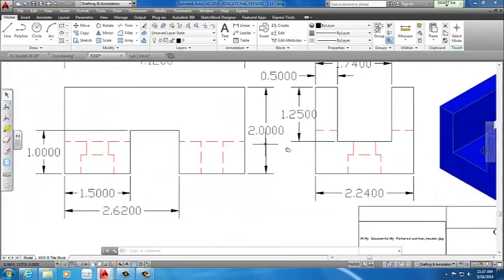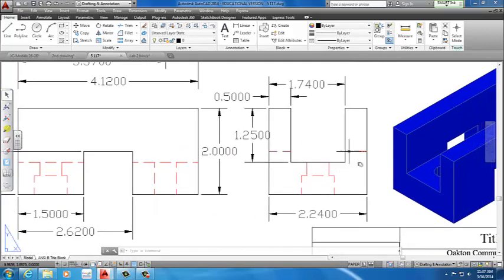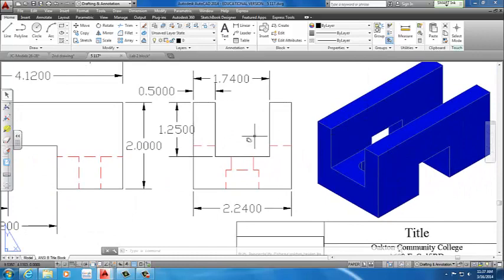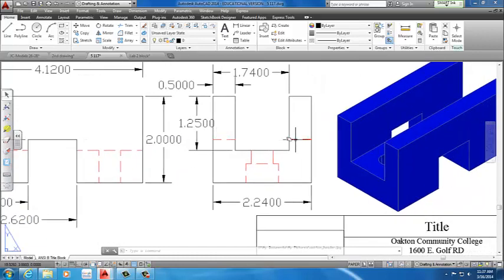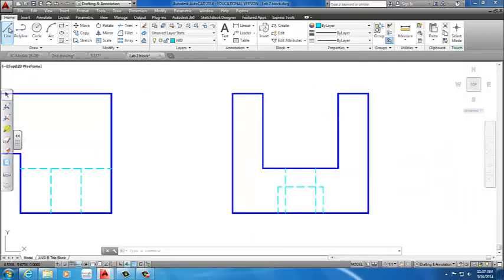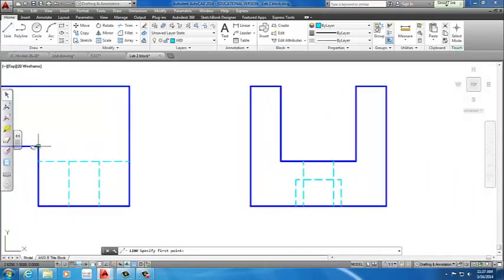I'm going to create a new viewport, a single section view from the center. I'm going to just create a box which is incorrect. But we do have to draw these two lines out here, so I'll double click inside, again, and use the line command. We can see the 3D object only, so I follow this line to give us a path. I change my view to like an isometric corner view.